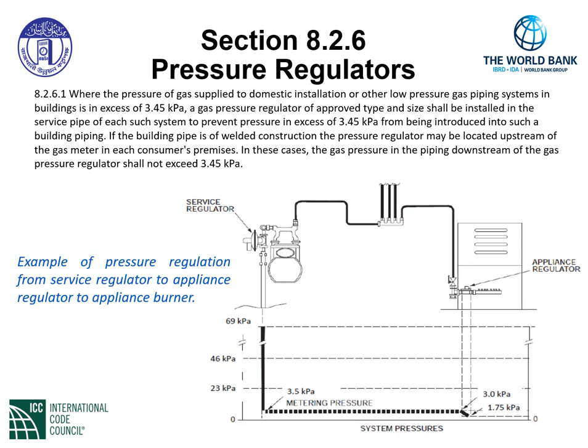That needs to be considered, of course, in the design of the gas piping system by the engineer, as well as referencing the appliance manufacturer's installation instructions. Appliance installation instructions indicate the maximum and acceptable pressure to be supplied at the appliance regulator for certain appliances. We further reduce the pressure from 3 kPa to 1.75 kPa as the manufacturer indicates to supply the burner manifold in the appliance.